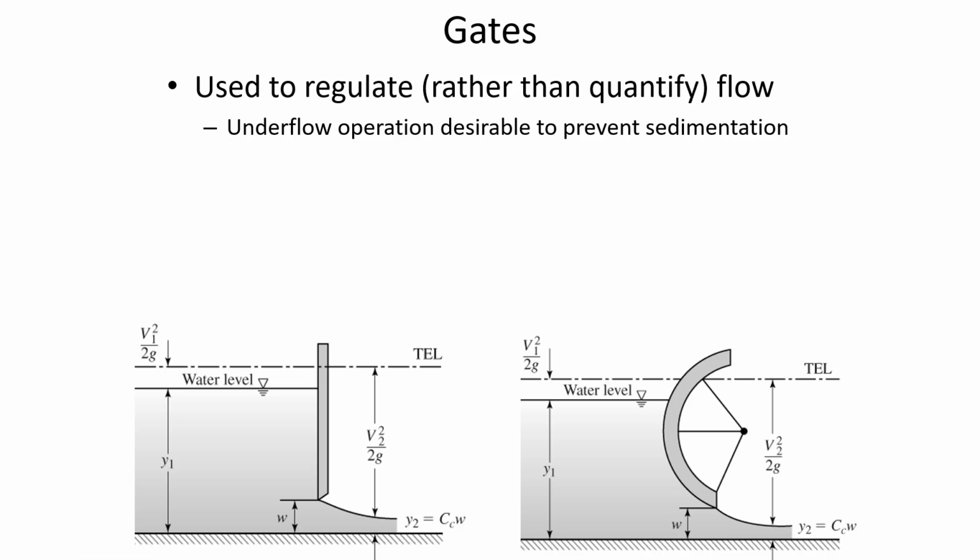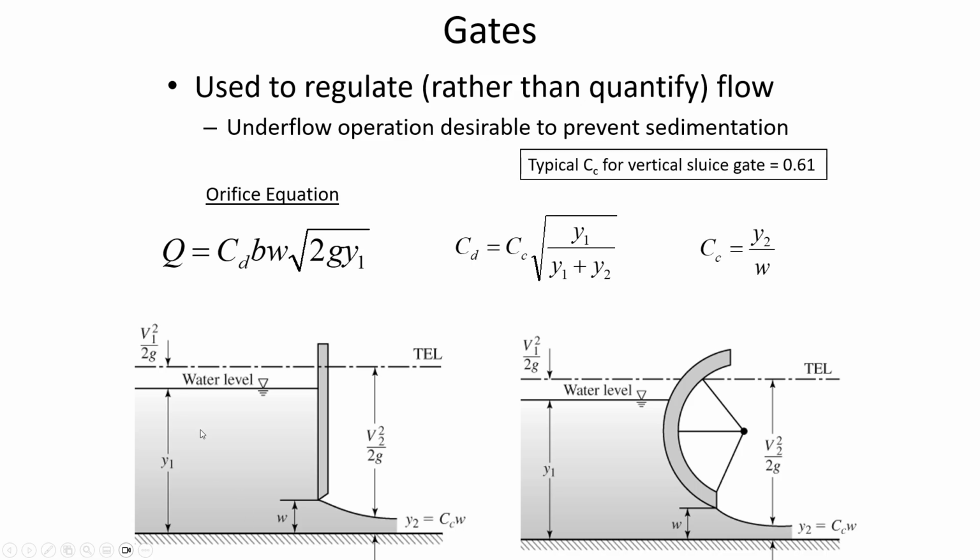You wouldn't want the scour velocity to be too high. For example, if you had soil or clay at the bottom of the canal, then it's possible that your supercritical flow here could be causing scour, especially depending on what kind of jump downstream. Remember, in class on Wednesday, we were talking about how different types of jumps, like an oscillating jump or a strong jump, can have some of their velocity vectors pointed downward towards the bottom of the channel. So an underflow gate with any kind of appreciable velocity is probably going to be armored at the bottom with concrete or asphalt lining, or maybe if it's a rock channel, that would be okay.